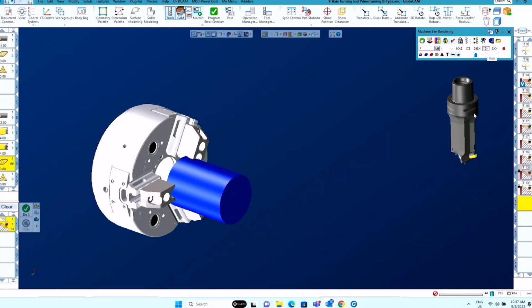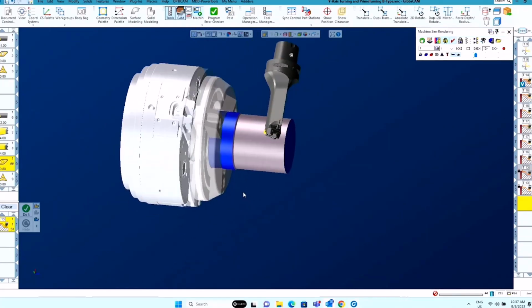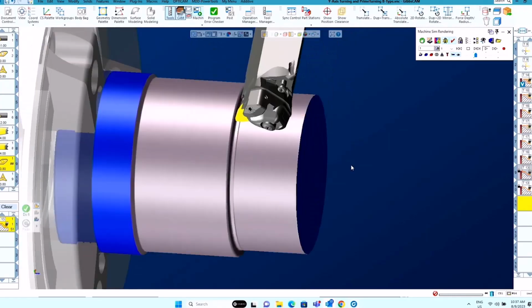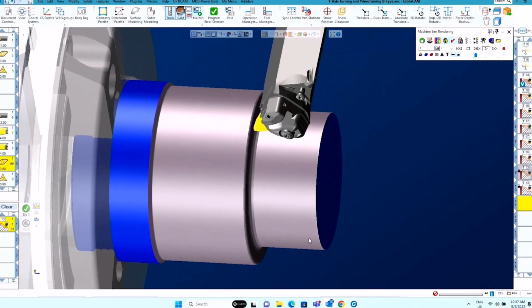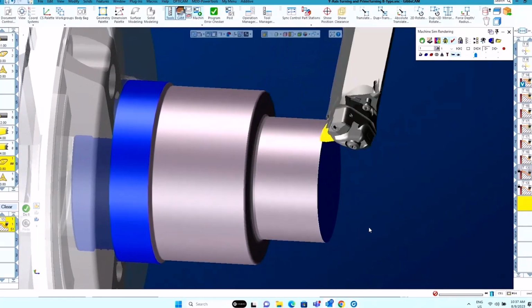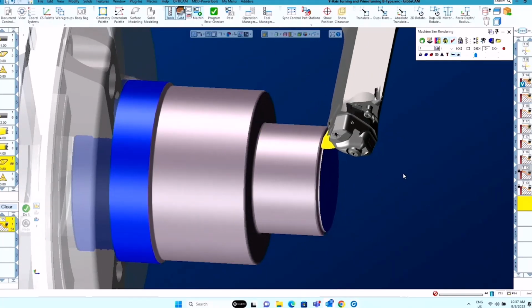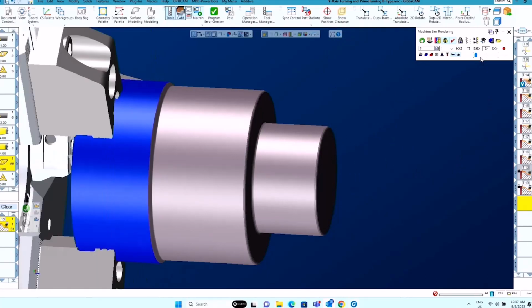So we're gonna see our tool rotating around to our B-type prime insert. Okay, prime B, and here we are machining. Let me rotate it a little bit more around so you can see a little bit better. There we go. Okay, it's a prime B insert. Roughing the material out, we come around the front there, and now we're gonna set up and machine the face of the part. Now we come up with our round button tool insert for our Voluturn operation.